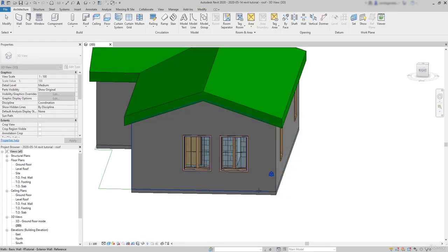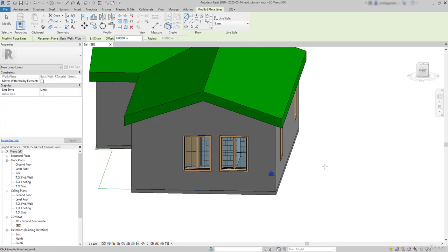Make sure the correct wall is highlighted the moment just before you click. And click only once. We may think nothing happened because the wall is not highlighted anymore, but you can always be sure that it was selected if you look at the placement plane. Finally, I can easily draw the lines using the snaps at the windows, and to connect to the roof, there are also intersections here.